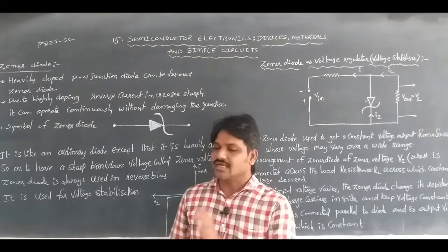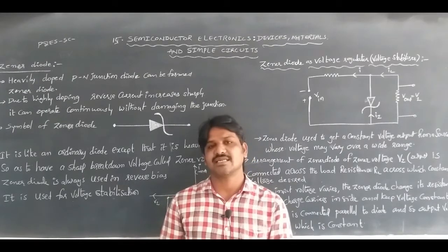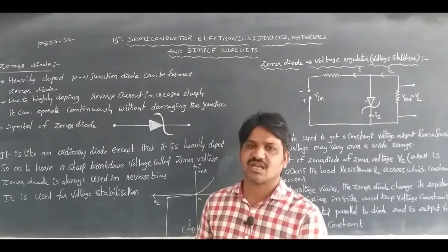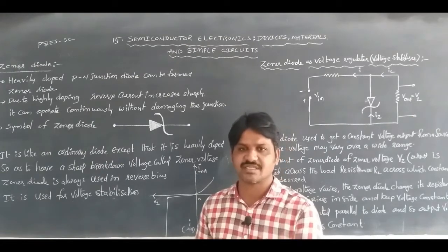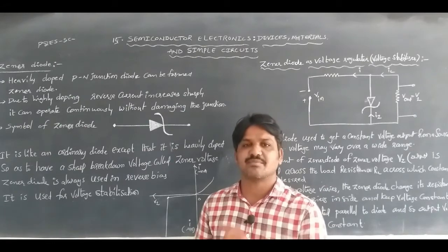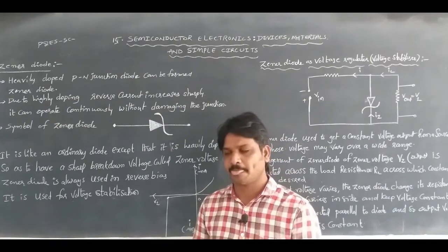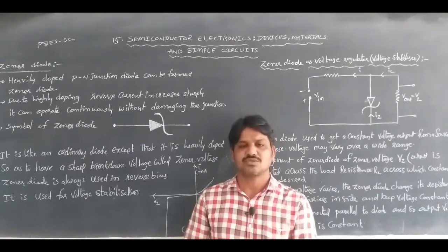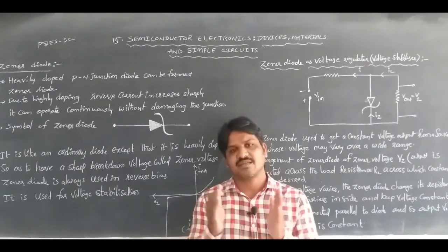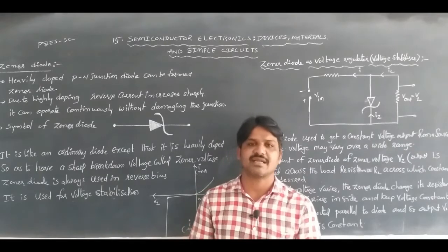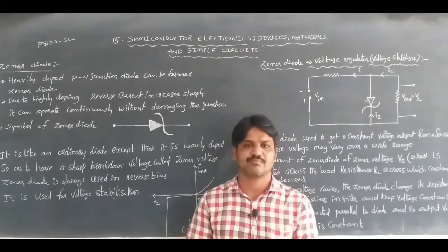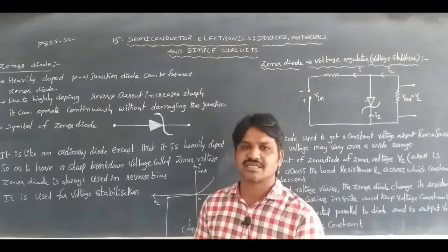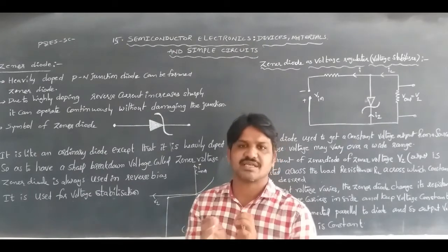In case the PN junction diode is connected in reverse bias, there is attraction between the positive terminal of the battery and the N side of the semiconductor, and between the negative terminal of the battery and the P type semiconductor. Due to the minority charge carriers, a small current will flow through the circuit. The depletion layer width increases, the potential barrier also increases, and we get zero output. Also a sharp breakdown will happen due to the minority charge carriers, and the junction will break down.